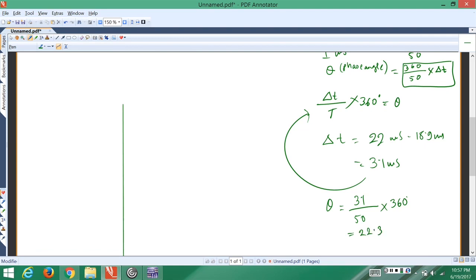If you perform a theoretical calculation on this phase angle for VR and Vs, the voltage source or supply, you will see it would be something like 21.6. That's what you get if you calculate, and we are getting something like 22.3, which is slightly off, probably because of how we took the time reading using the cursors.